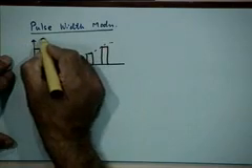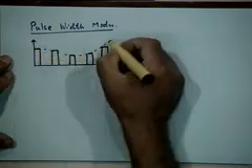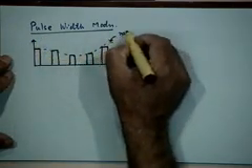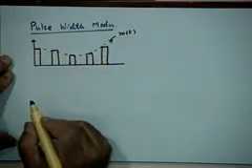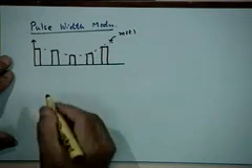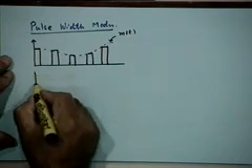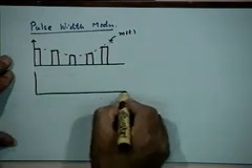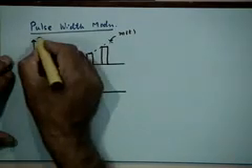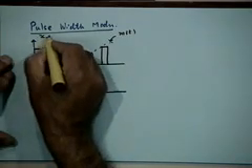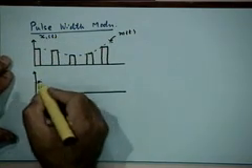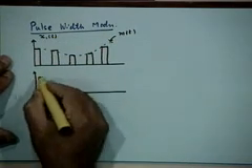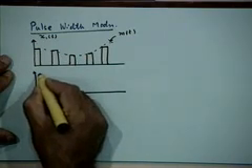This is the message signal m(t), and this is a PAM signal corresponding to this message signal, right. Now, to this signal, let me call this x1(t), we simultaneously generate another set of pulses of constant amplitude, but whose shape is triangular in nature.